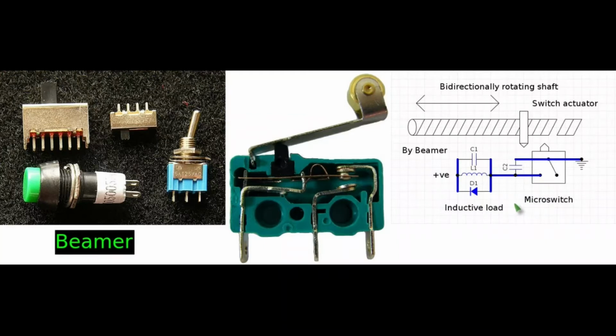Every 3 months, approximately 4 months, an engineer had to be sent out to this equipment, and the micro switch had to be realigned because the mechanical position of this shaft was critical. Incidentally, the whole of this equipment was in a semi-critical application. So it was very important. So the manufacturing company had to obviously pay for an engineer to realign this micro switch.